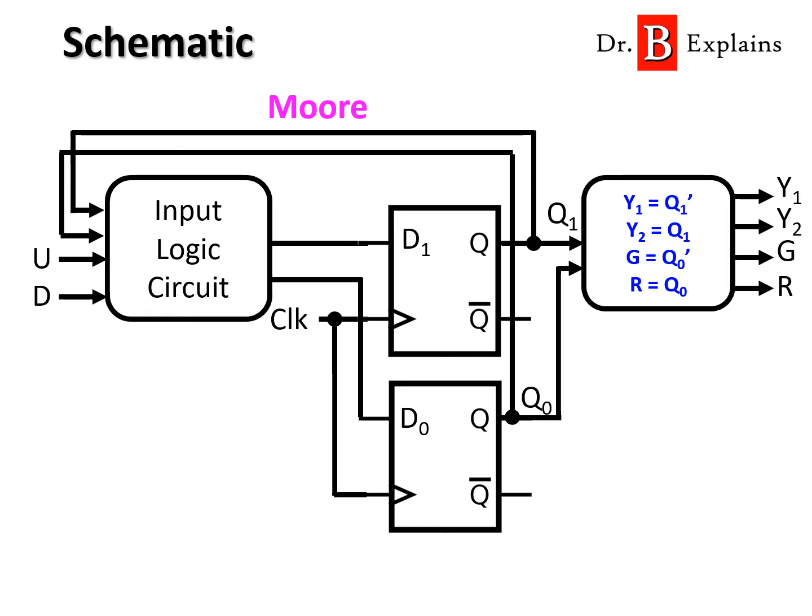So now we decided on D flip-flops. We need to think about the flip-flop input table. What is the flip-flop input table? It tells us what we need to put at this input so I can make my Q plus, my next Q, the one that I need, right? So what do I need to put here so that Q plus is whatever I want?